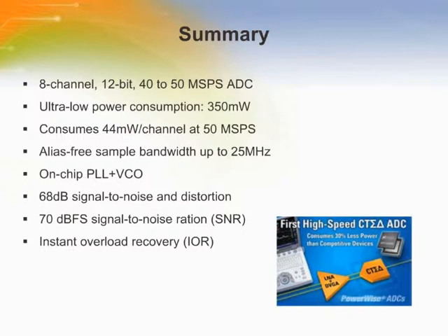The ADC 12EU050 analog-to-digital converter solution offers 12-bit resolution at an output rate up to 5 times the fastest currently available sigma delta analog-to-digital converter. The power dissipation is 30% lower than pipeline ADCs. The CT sigma delta technology on which the ADC 12EU050 is based also offers significant inherent anti-aliasing filtering and provides a low noise, easy to drive input stage.